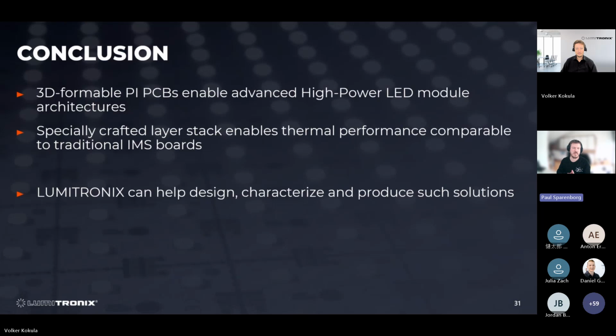If we are talking about very demanding applications, we're sometimes talking about heat generation in the area of hundreds of watts, maybe even kilowatts of heat. In these areas, plastic is usually not working very well anymore. But for smaller products with small amounts of heat generation, in the area of maybe a few watts only, it might be a very viable option.